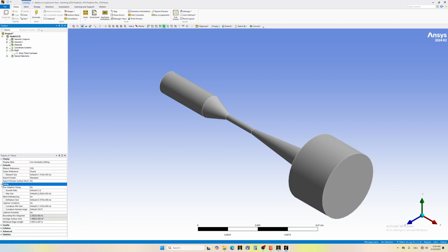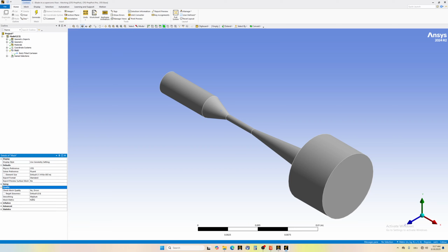Now we go to mesh sizing, quality, smoothing, high. The mesh metric shows us the quality is just a statistic, so it will not change anything here. And at meshing, let's put 0.00005, let's say. This will give us about 1 million something cells.